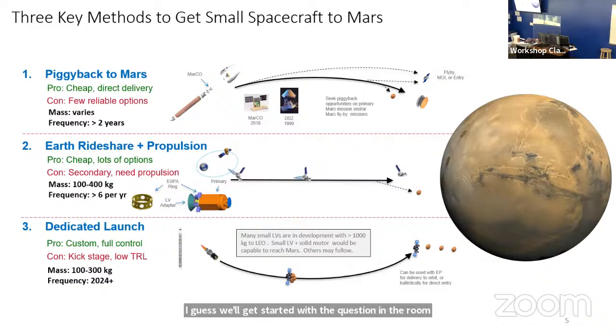This is Alejandro Soto. I have a question for Ryan. 7 or 8 years ago, some of us at SWRI were looking at large N CubeSats, like 12U's and 24U's, trying to get them to Mars off of a lunar transfer orbit. So we looked at solar electric propulsion, and we found one of the problems, of course, is getting enough solar panels on there to get enough power. But the other problem was the availability of the solar electric propulsion devices, the community building those, at least on the low end.